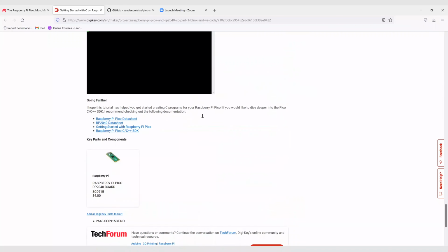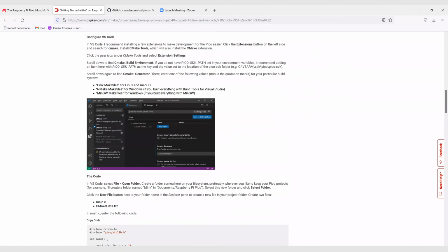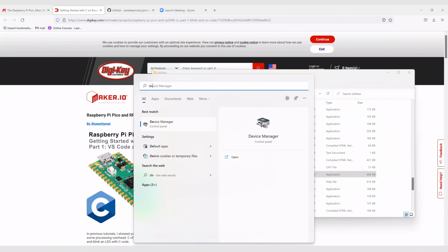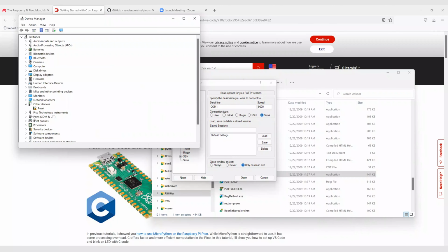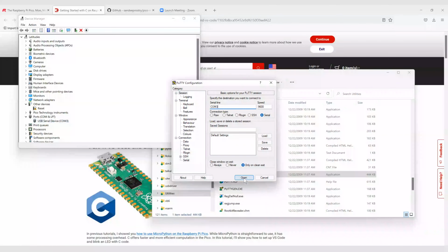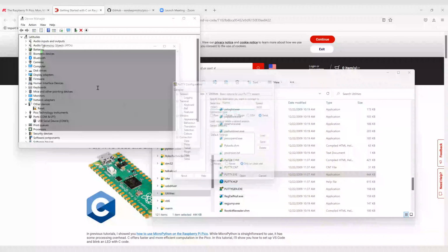So, oh, there's one thing I did not show. The project has a USB interface console to the PC over a COM port. We're going to cover USB at some point, but the Pico does a really great job with this, making it so easy. So printf just goes right to the USB port. And you can see there's a COM3 here. So if we go to COM3, the speed doesn't matter.